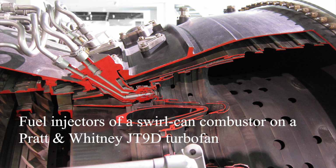In canannular and annular combustors, the flame can propagate from one combustion zone to another, so igniters are not needed at each one. In some systems, ignition assist techniques are used. One such method is oxygen injection, where oxygen is fed to the ignition area, helping the fuel easily combust. This is particularly useful in some aircraft applications where the engine may have to restart at high altitude.